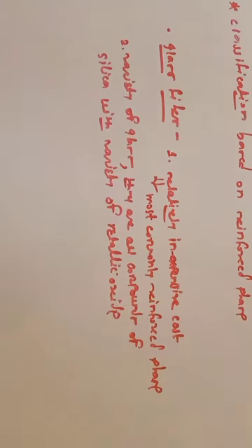So why are these glass fibers used in the formation of composite material, or why do they act as a reinforcing material, why do we reinforce them into this matrix material? Because they have a relatively inexpensive cost, the cost is very low for this fiber, and therefore these are the most commonly used reinforcing phase in this composite formation.